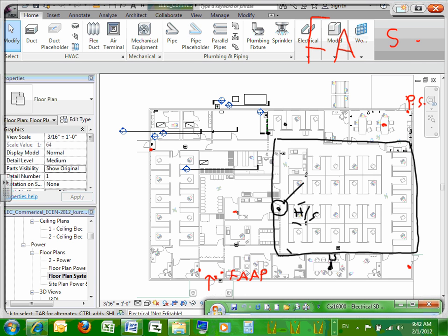Same thing in the restrooms. Doors closed, obviously, and pretty soundproof. So if you've got a horn strobe out in the corridor here, it might not reach in there. You need to know that there's an alarm and you need to get out as soon as possible. So strobes in both restrooms.